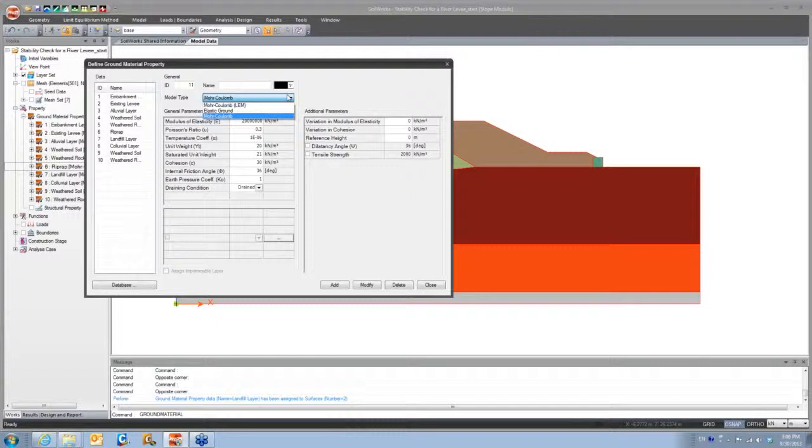So for example, if you're doing an excavation or retaining wall type project, you'd also have the hyperbolic constitutive model, Drucker-Prager, Tresca, Hoek-Brown for your rock materials. So all those constitutive models are available to you. It just depends on the module that you're using, each one has different constitutive models to choose from.